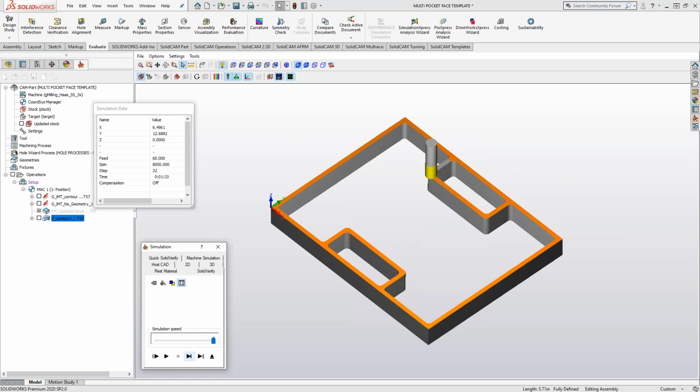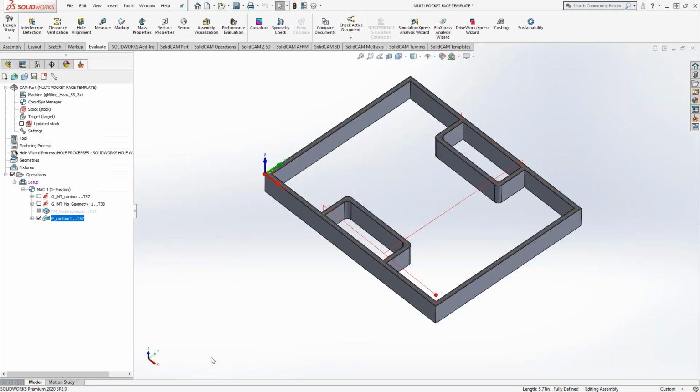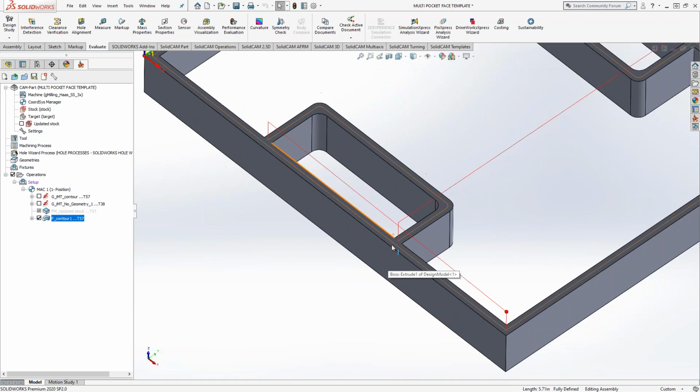So obviously with the tool going down the center line, there really isn't a left or right side, but by having all the chains going in the same clockwise direction, when I give it an offset, they're all offset in the same direction. So that idea is still there. Mark, how would we extend those windows on the front and back side so the tool doesn't start right on the part? Yeah, I saw that as well. So that's a really good question.